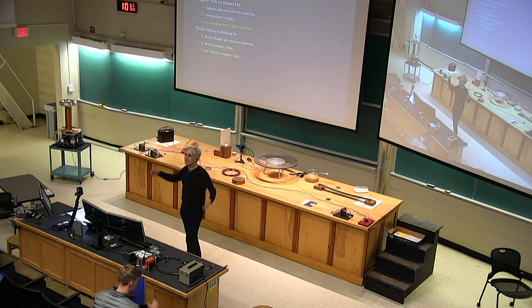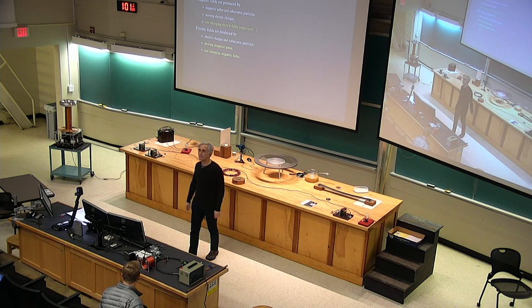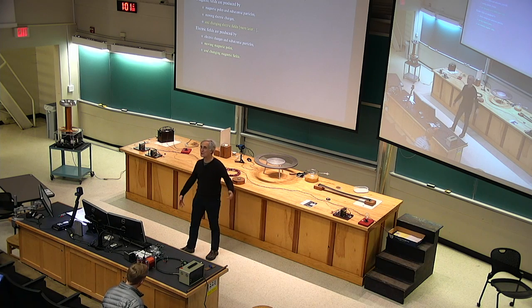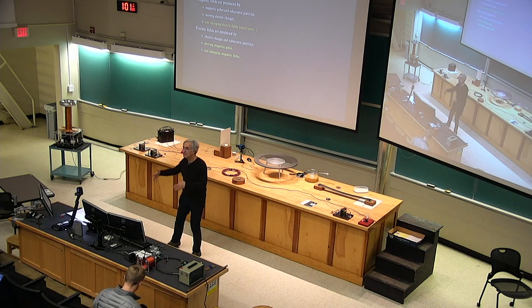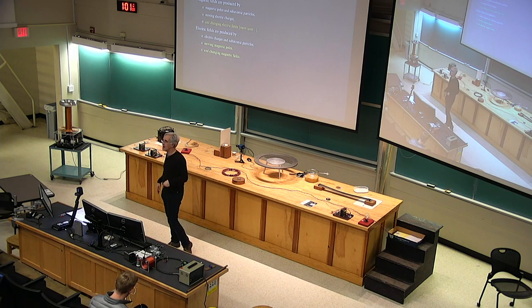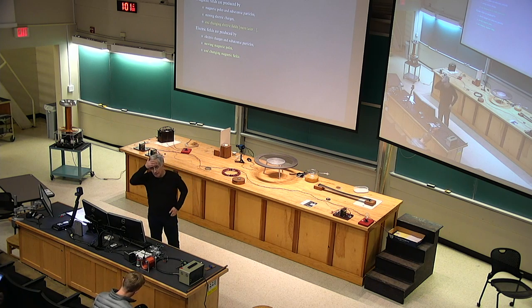So back off on the current. How do you do that? Crank up the voltage. But you can't deliver at high voltage because it's too dangerous. So you have to shift gradually to lower and lower voltages and higher currents to deliver the power.